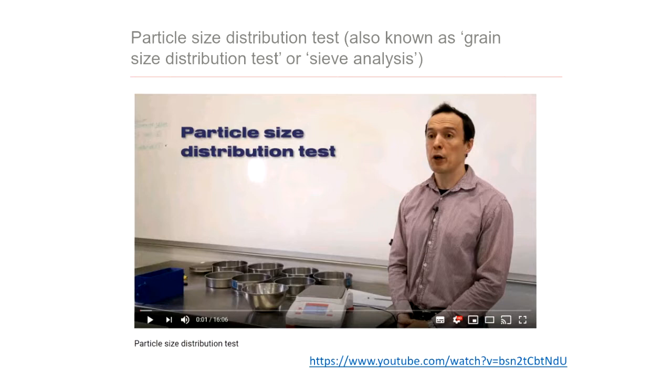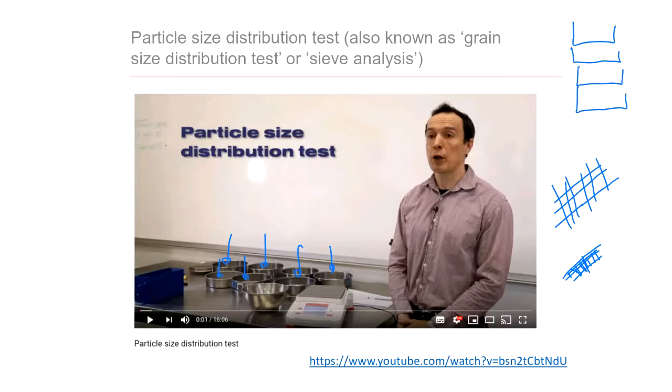It's pretty simple. We have sieves, and the sieves have all different openings, what we call mesh. It's kind of like this. This is a coarse one, or a really, really fine one. So this mesh will define the size of particles. And then we set it up as a stack of sieves. The last one, the one that we put at the bottom, is called the pan.